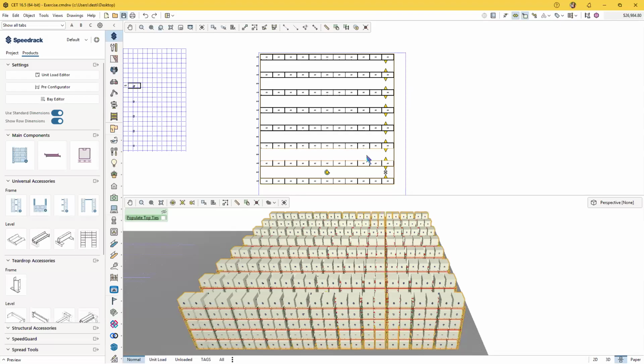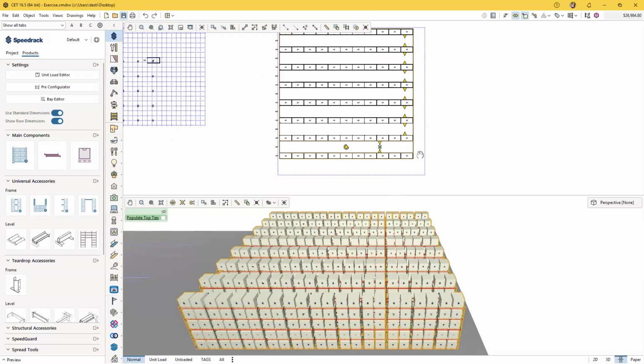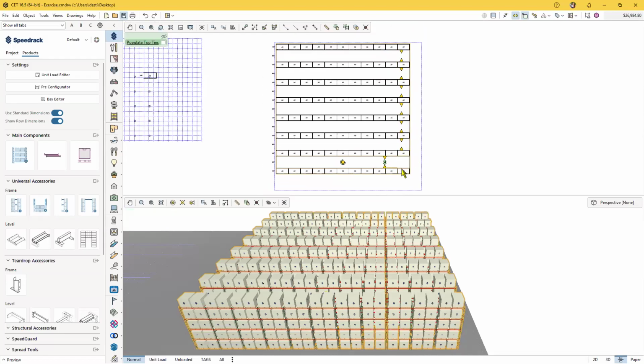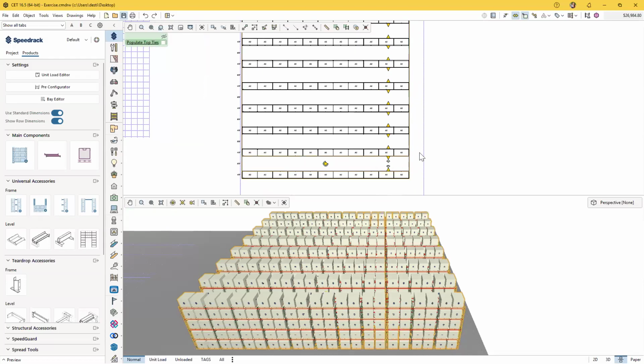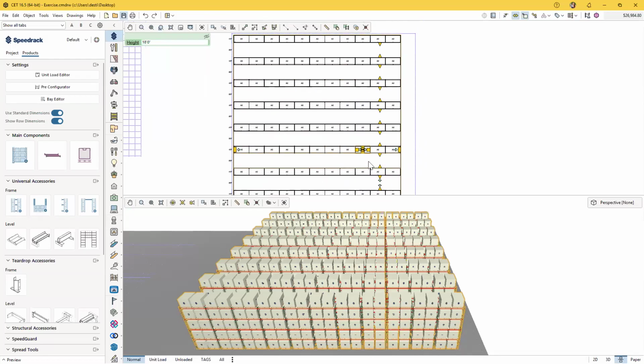You need to kind of think in this system manner. So let's say that we want to create maybe one less bay per row here. We want this whole system to be just a little bit shorter because we want a little bit more clearance, maybe on this side, maybe even two bays shorter. What I could do is, while I'm in group select, I can go ahead and select any of my bays here, and I will get a little stretch node on the side.